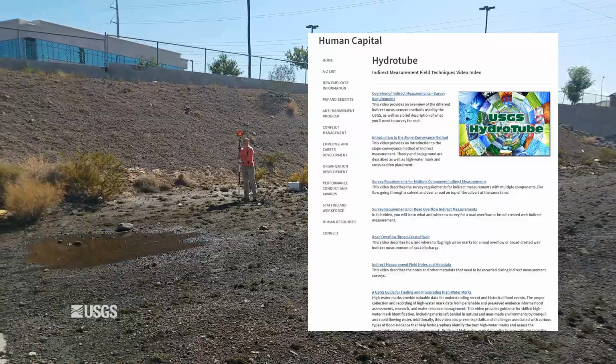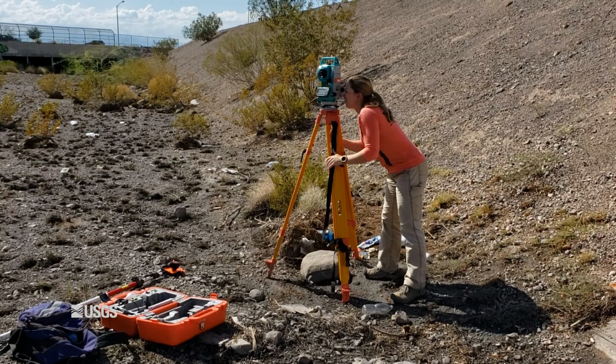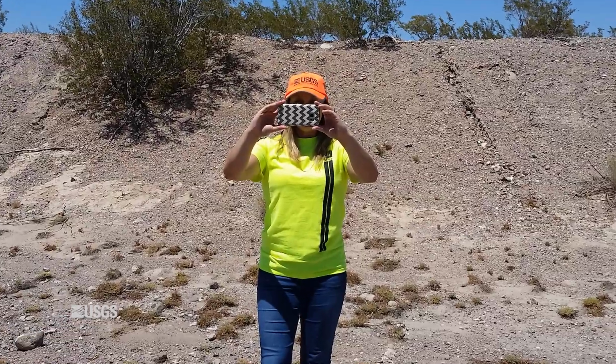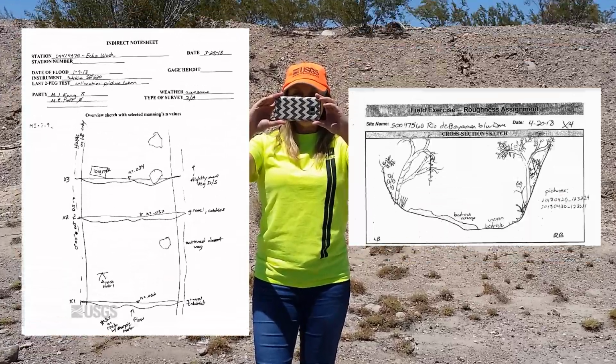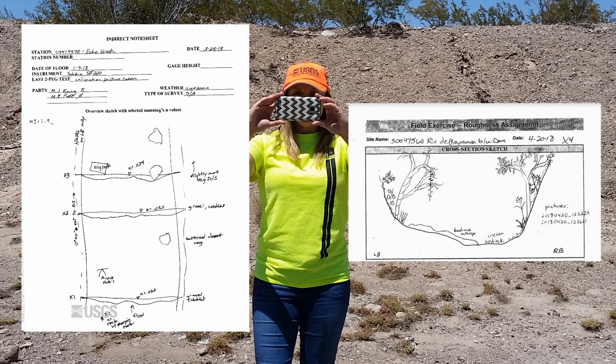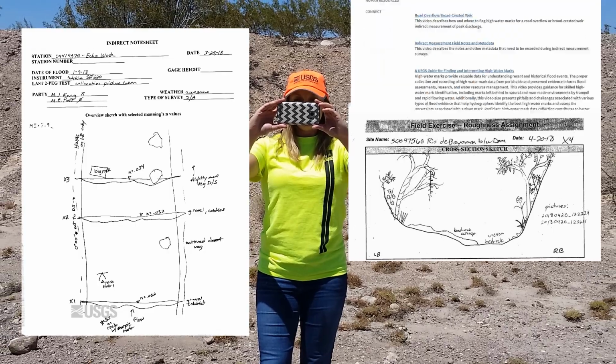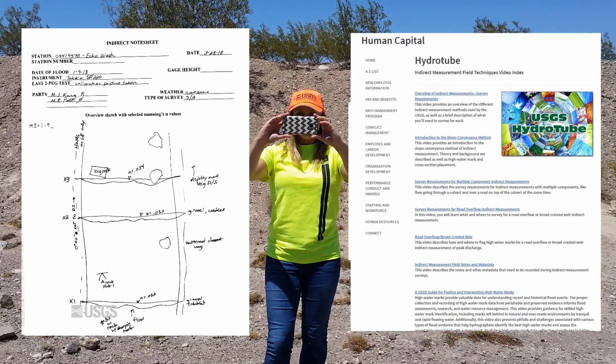At the end of the survey, break the HI to turn and close the circuit by taking a final shot on your starting point. Take pictures, draw your plan view and cross-section site sketches, and estimate end values for each cross-section. You're done. You can find more information on the types of notes to record and what to put on your site sketches in the Field Notes video.